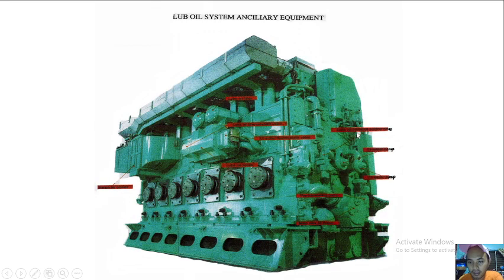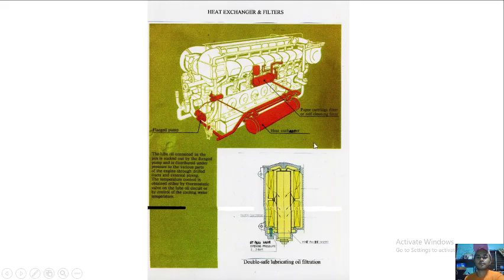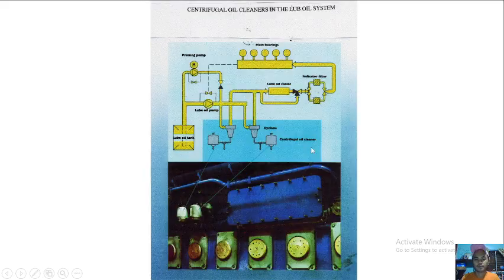Then the lube oil pressure controller. We have two centrifugal oil filters, so both are used, but you can clean one by one. Do not clean both at the same time.